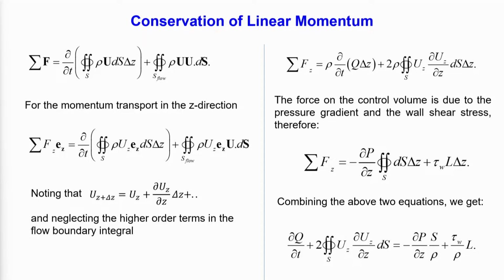What you were talking about is change in velocity, similarly change in pressure. So, change in pressure is just like the Taylor series, just replace u with p. So, that is the pressure gradient with respect to z into delta z. That is your difference in pressure, and that times ds is the force. So, that is the force due to pressure.